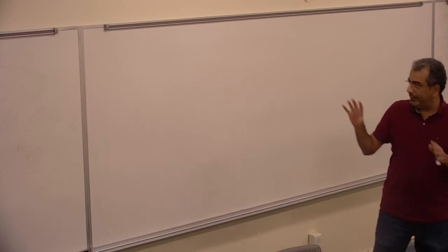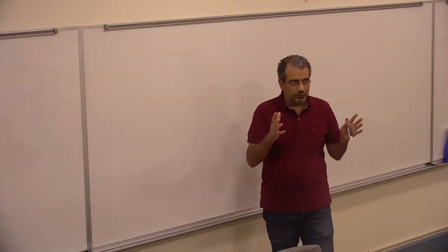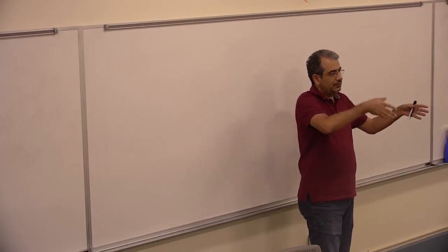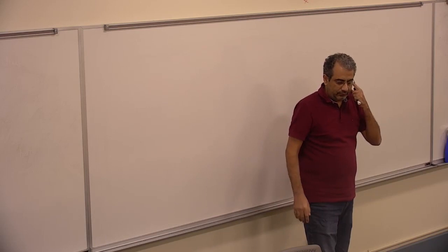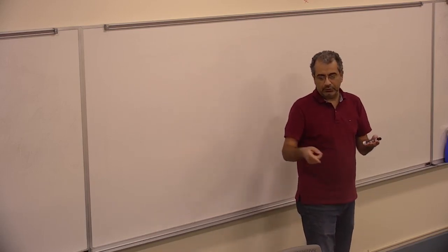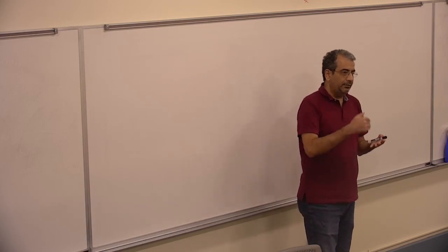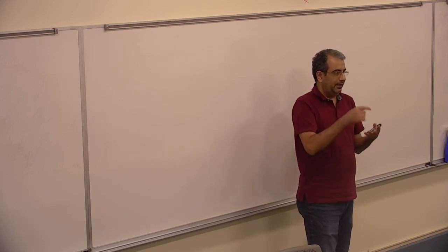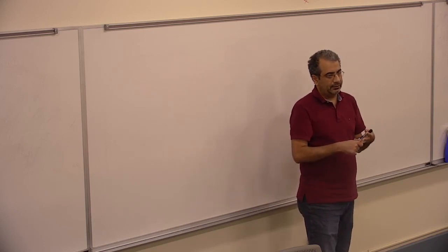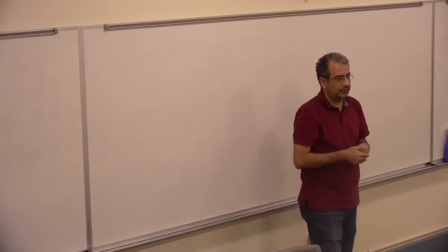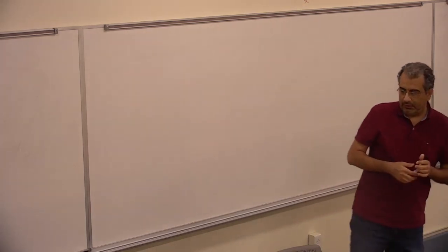So I gave you just the quick idea of how we do that. You have to establish the X at the beginning of the beam and keep cutting through the beam and find the moment and shear based on that. Remember that before you do some examples. Anytime there is a change in the force, we need a new section. And anytime we have a distributed load, we need one section somewhere in the middle of that distributed load. So let's look at a couple of examples.